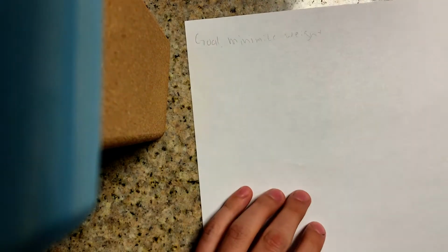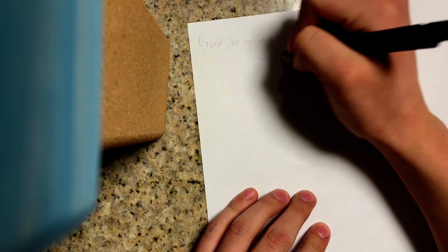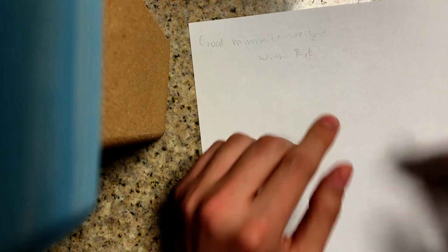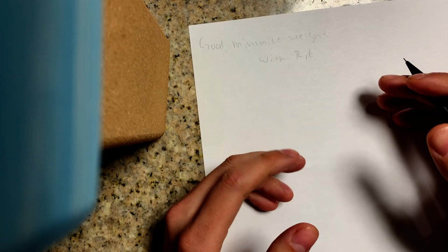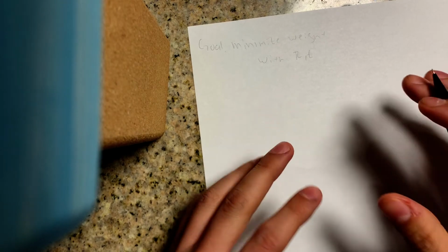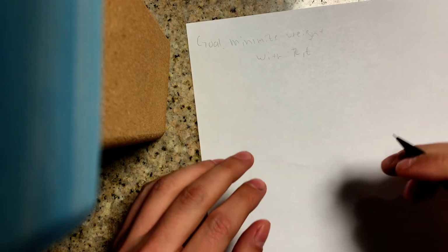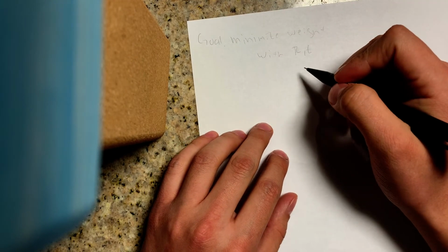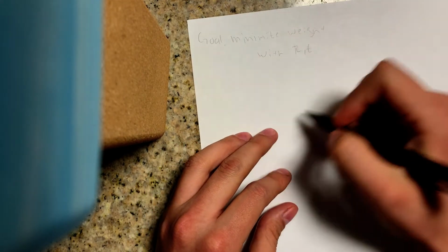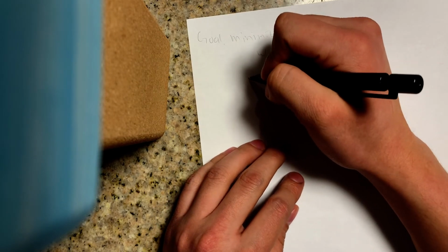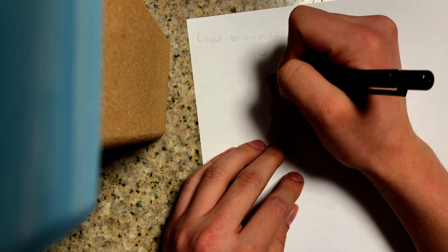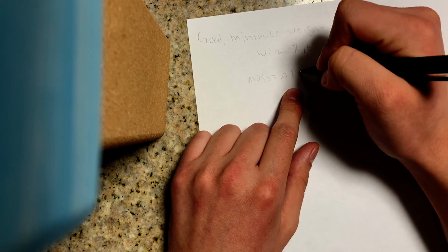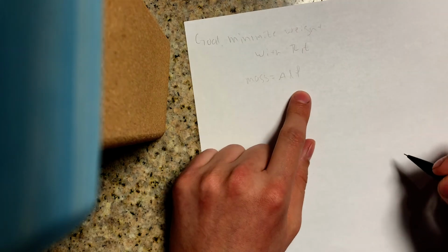In order to minimize the mass when we have a fixed length, and obviously in this scenario a fixed density, we need to minimize the area of our cross section, right? Because the total mass is going to be equal to the area times the length times our density.